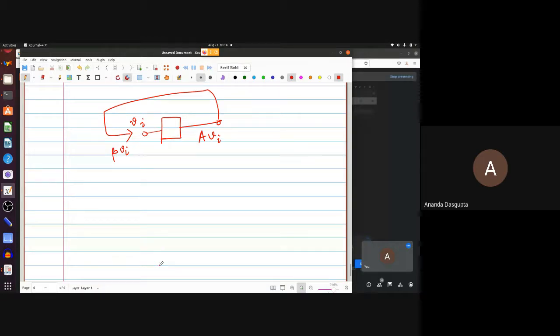then what happens? This is, remember, an amplifier, not an oscillator. This is just an ordinary amplifier which takes an input, produces an output. But if you fed back the output, a part of it back to the input, then what can happen? In principle, what can happen is this. The fed back input can actually produce another output that will come back again, that will add up, that will add up, that will add up, and ultimately you end up with an output without an input. The output will keep on growing without an input.